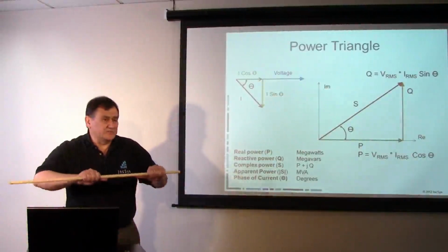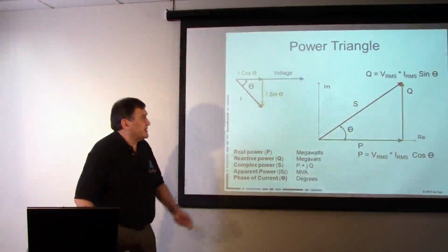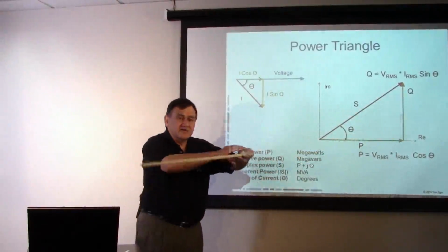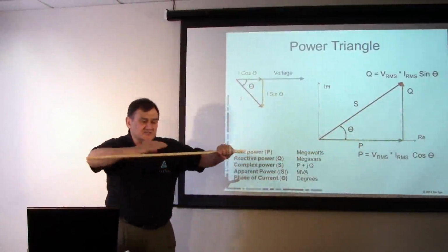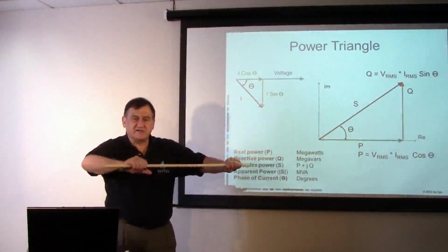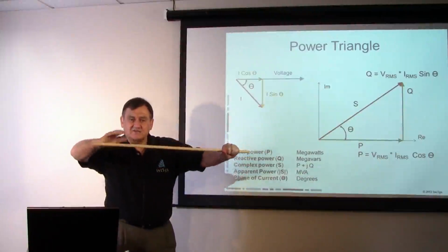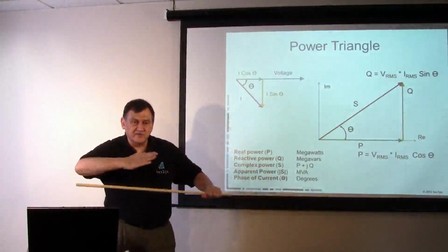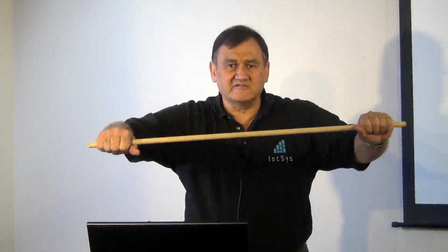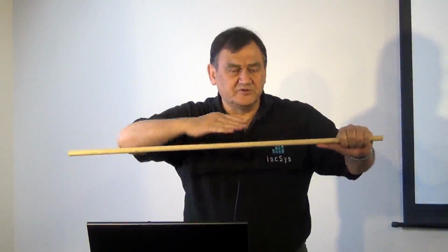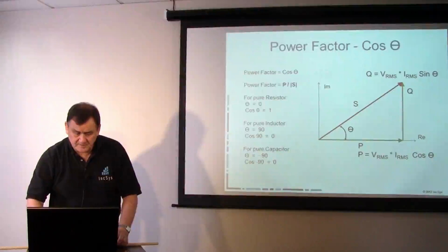That's a good point: at one end, I could have 0 megavars and be under the rating. At the other end, because it's a net absorber, I could have a very high amount of megavars, and those conductors at that end could be overheating and sagging. So you've really got to watch the megavars at both ends. Like I said, the megawatts are a nice uniform thing. What comes out will be a little less than what goes in. Megavars are totally nonlinear, because that line can either absorb or produce megavars. And we'll get into that whole characteristic a little bit later.